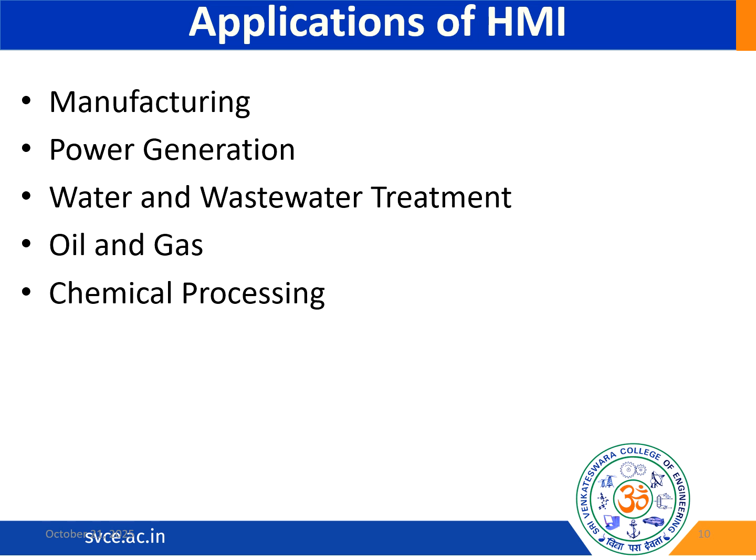So basically you would have understood the difference between HMI and SCADA, and you know the purpose of using HMI. So this HMI communicates with programmable logic controllers. HMI screens can be used for single function like monitoring and tracking, and it can also perform more sophisticated operations like switching machines off or increasing production and speed depending on how they are implemented.